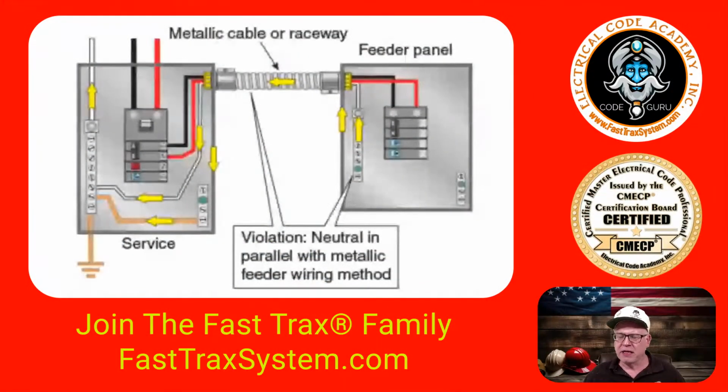So right here, whether we can just remove this screw or not and make this compliant really gets into a deeper discussion on what type of wiring method we're using. And in this illustration, it's evident this is not going to be MC cable. And it's evident that we're not going to feed a panel like this with a 20 amp circuit.